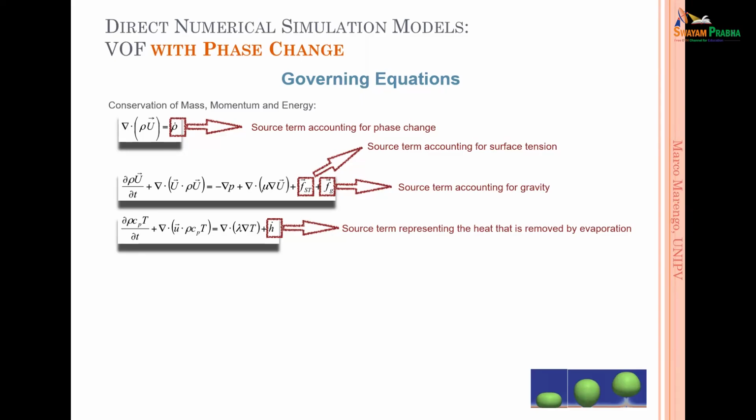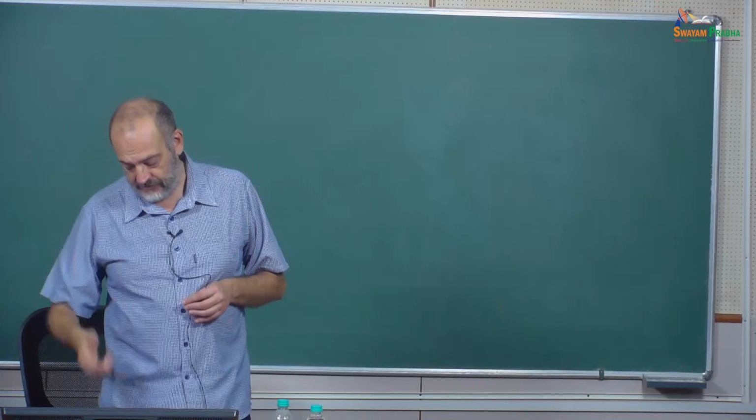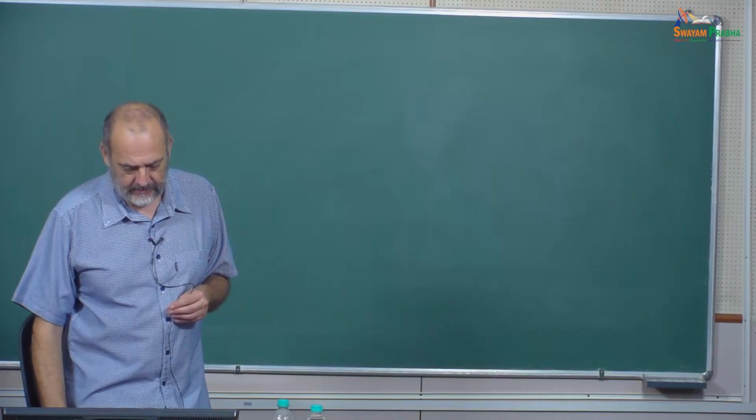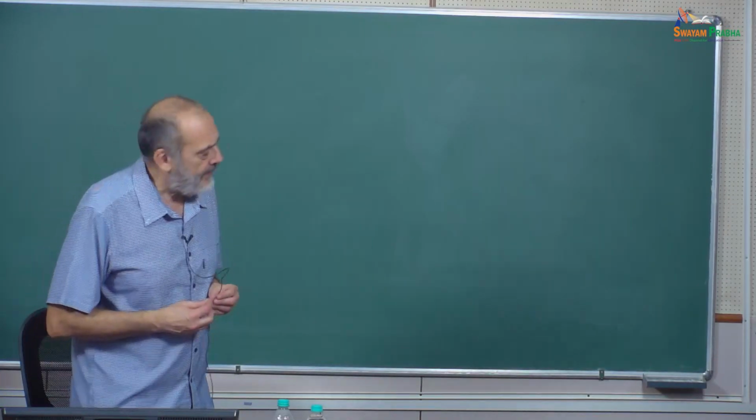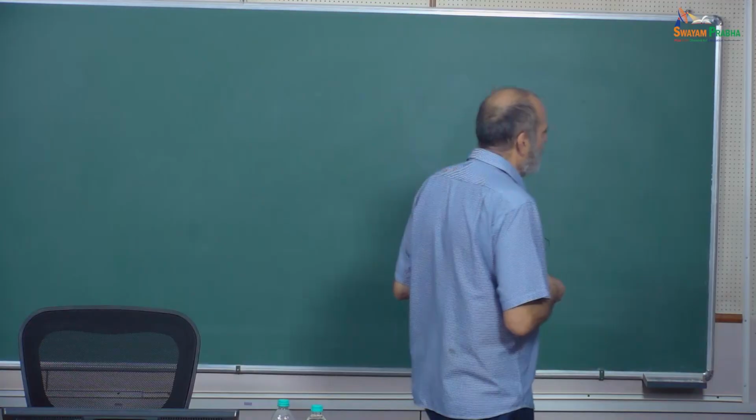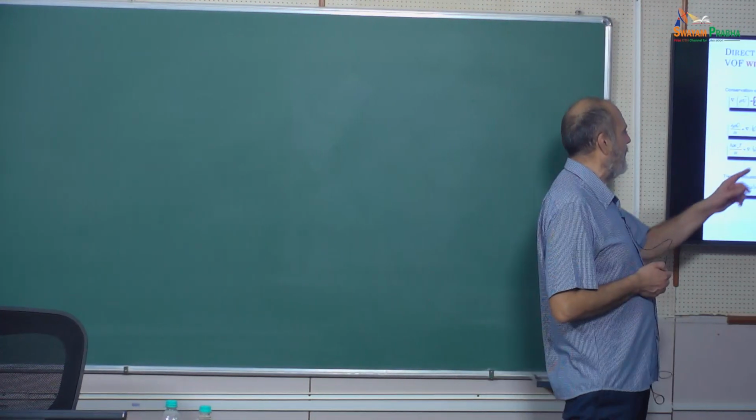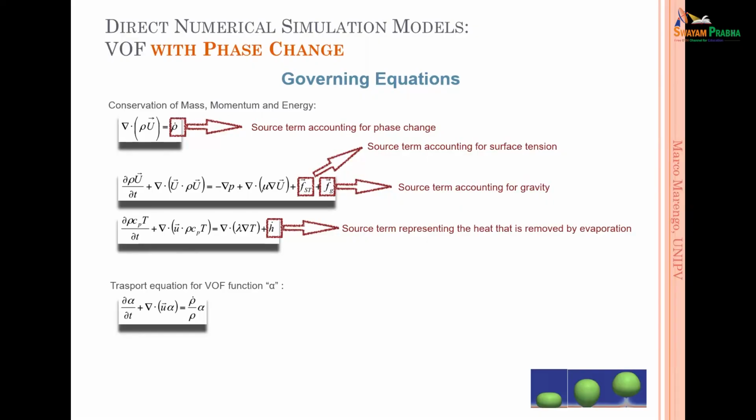But in fact, in the general theory I did, there was also a term to consider, but in this case, it's not. And the big change is also with the phase transport equation, because we need to consider that we have a density variation in time due to the phase change. The local and time variation of the density means that the transport equation is also changing form.